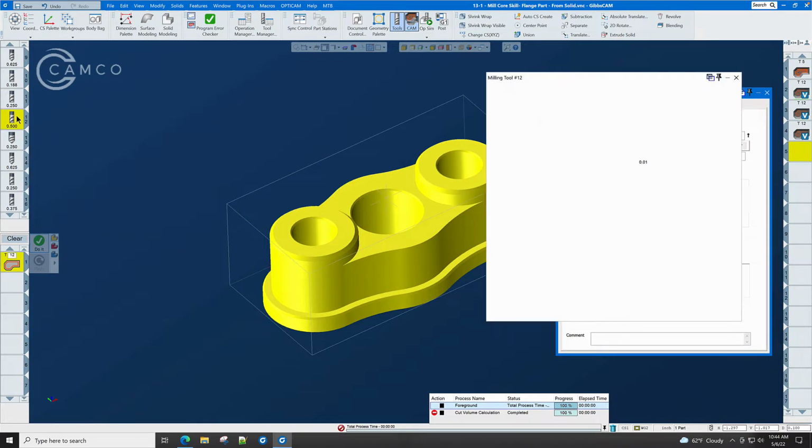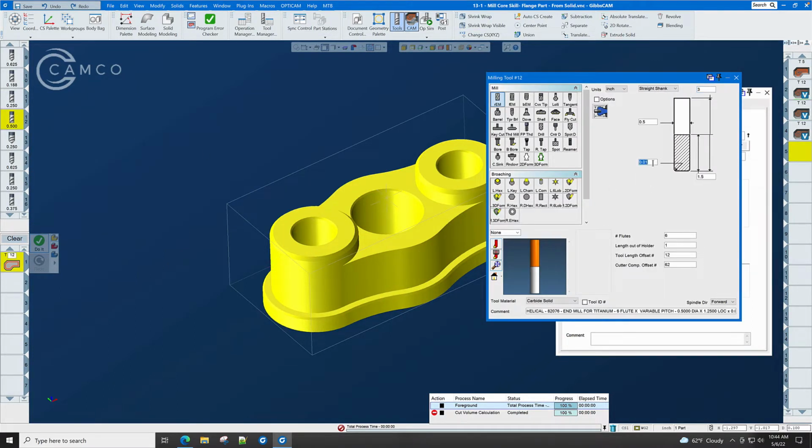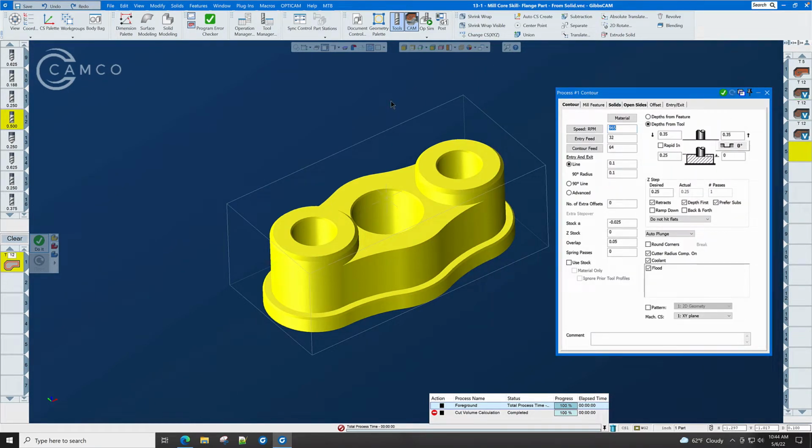On this finishing end mill, let's use a 0 radius on the bottom. Here we have a plain contour. Our RPM volume mill told us is 5100, and we're going to use 30 inches a minute feed rate for entry and 60 inches a minute feed rate for finish, and we will get a beautiful smooth finish.